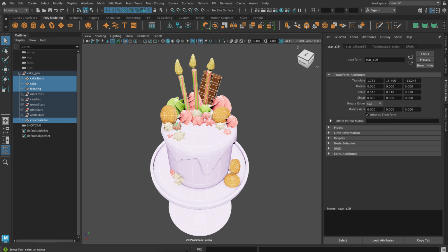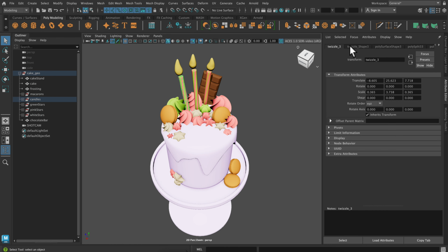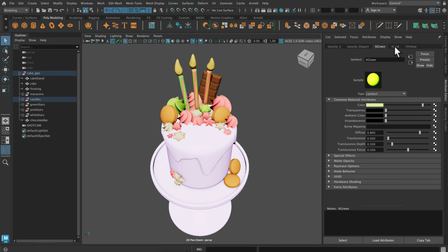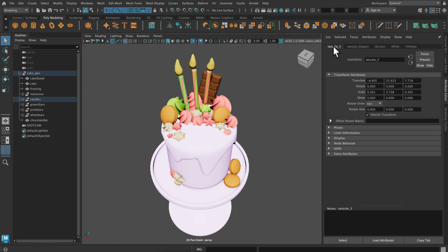So you can see in my attribute editor, let's just grab one object, that this is all of my construction history, all of these little tabs here showing these poly splits and etc. When I delete my construction history, they should go away. There you go. And now I'm only down to the different materials that are on my model, a shape node, and just the object itself.